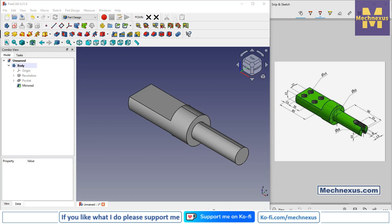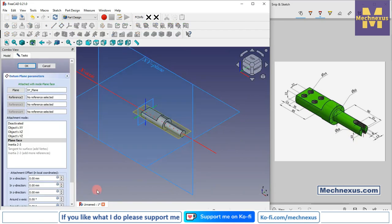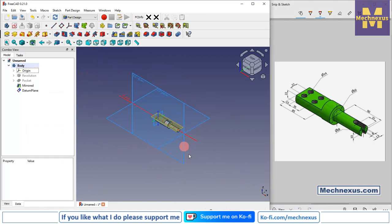Now we will create a tangent plane here. So for this we have the diameter of 28, and we will select this plane and click on the datum plane, and in the Z direction I will provide the value 40 mm and click on OK. And here is a blue tick, so press F5 to refresh it.